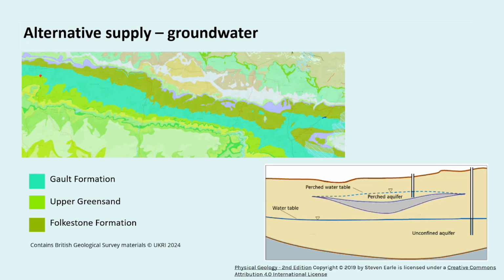Horsham District Council specifies that a planning application involving a borehole for the abstraction of more than 20 cubic meters of water a day must be supported by groundwater investigation consent from the Environment Agency, a hydrogeological assessment of the water yield to confirm that sufficient water is available year on year and throughout dry seasons, water quality assessment and a treatment, sampling and testing regime to ensure that the water is maintained at potable quality, an impact assessment considering receptors that might be affected by the new abstraction, and also an abstraction license from the Environment Agency.